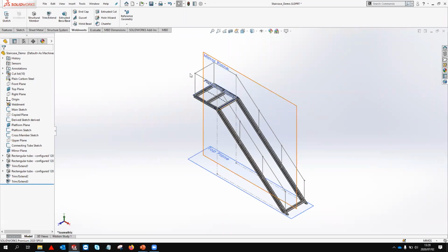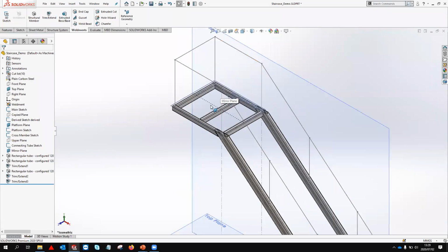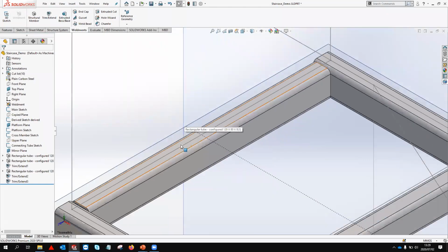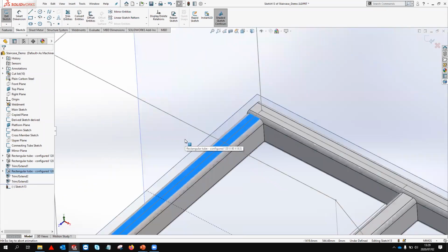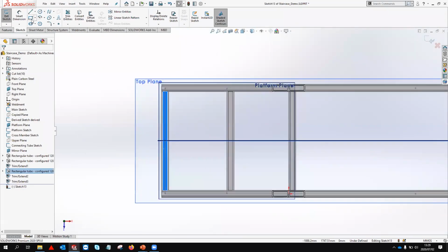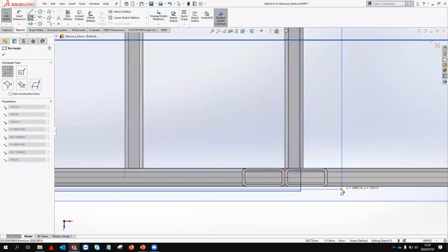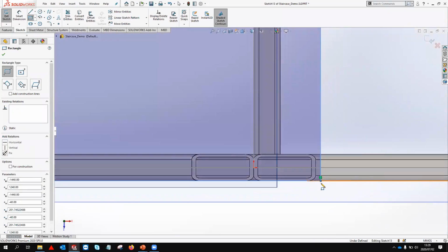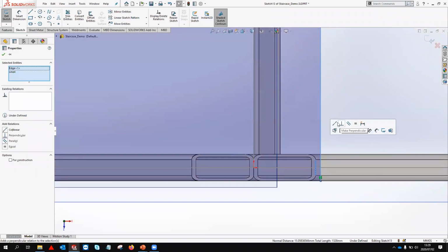Before we do the handrails, what I'm going to do next is create a platform first. So for my platform, I'll just create a new sketch on this face over here. Just a normal 2D sketch where I use a rectangle. And notice how I don't use dimensions to specify the size of this rectangle. Instead, I use the existing geometry to identify the position of my rectangle.